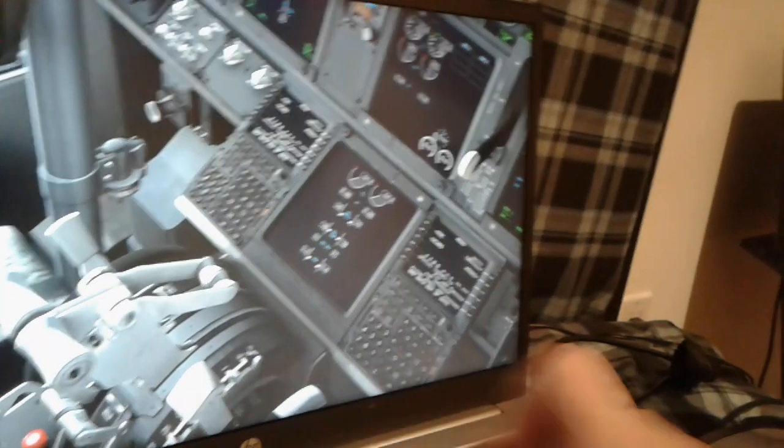Just gonna use the flight management computer. So now I'm gonna create a flight plan using the flight management computer of the Boeing 737-800 new generation aircraft. We're gonna connect in flight with the autopilot in the lateral and vertical navigation modes, and also we're gonna see in the navigation display the flight plan we're gonna create.